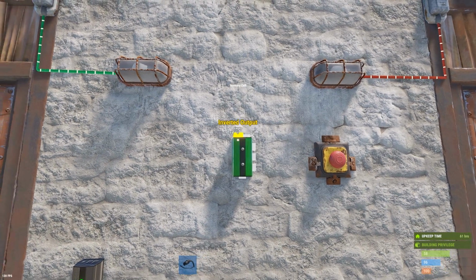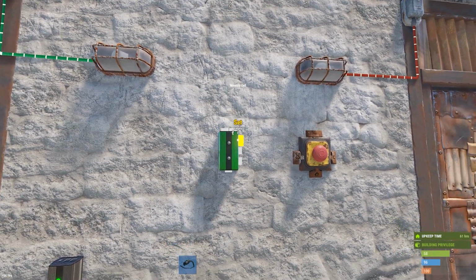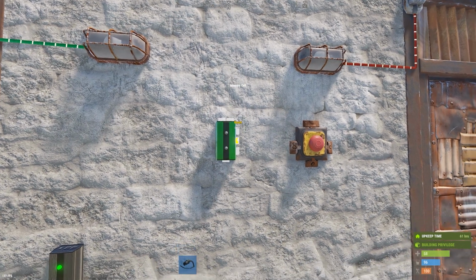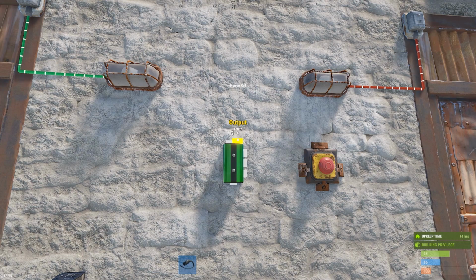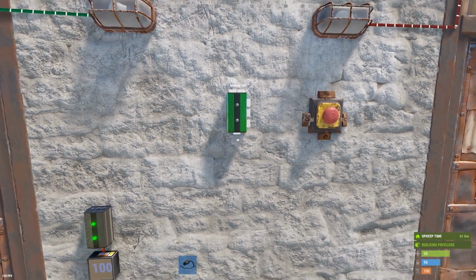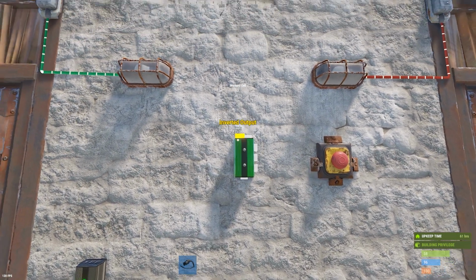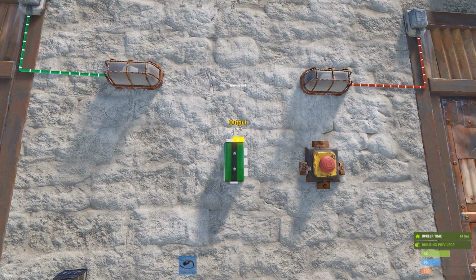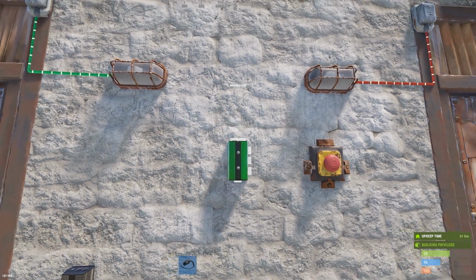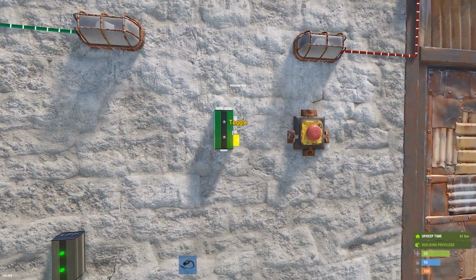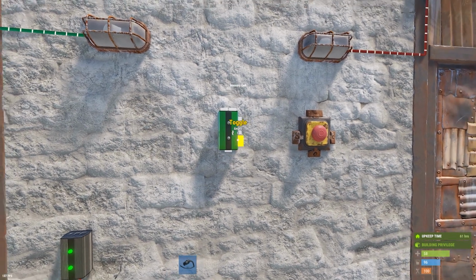All it's doing is swapping between these 2 based on what happens with these. If you reset it, it's going to swap to the invert, and if you set it, it's going to set to the output. Whatever power is coming in here, it's just routing either out this way or out that way, and that's all it's doing. There's also a toggle function we don't use for this circuit, but all that does is every time it receives power, it toggles between them with just one input.